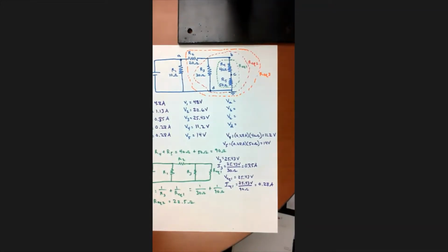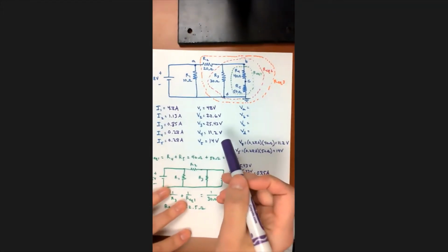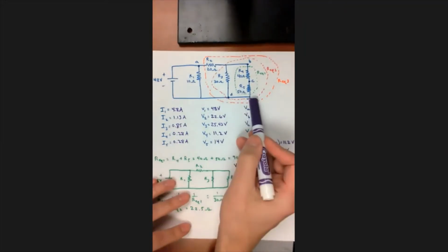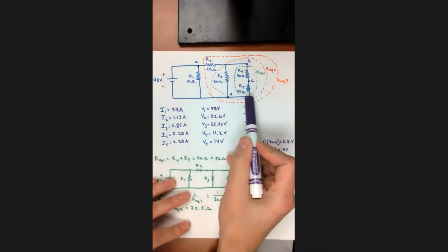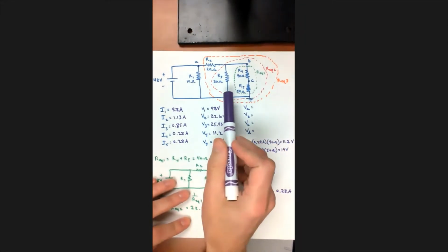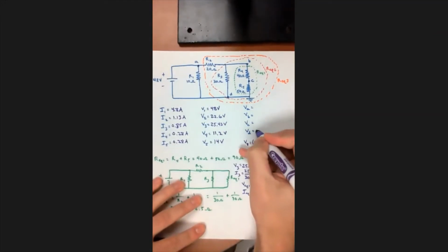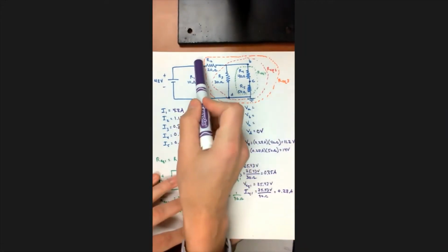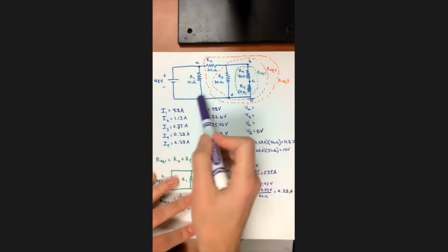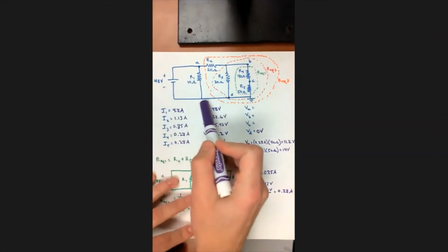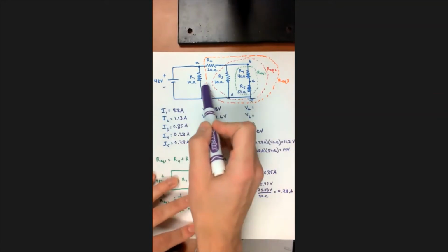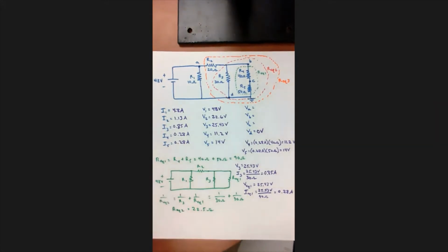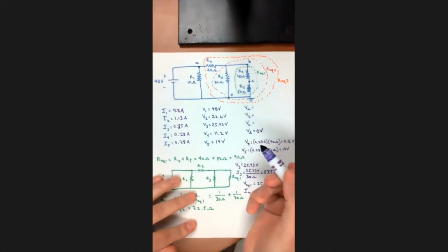All right. The last thing here is to calculate the voltage at these nodes, node A, B, C, and D. So the easiest thing to do is to start from ground. There's a symbol for ground. So that's at 0 volts. So we're basically told that the voltage at D is 0 volts. So write that in. And then the easiest way to get from ground to point A is to go through this voltage supply. So this is all at 0 volts because it's all connected with no load in between it. This is all at 0 volts, and from here to here, I gain 48 volts. So the voltage at node A up here must be 48 volts.